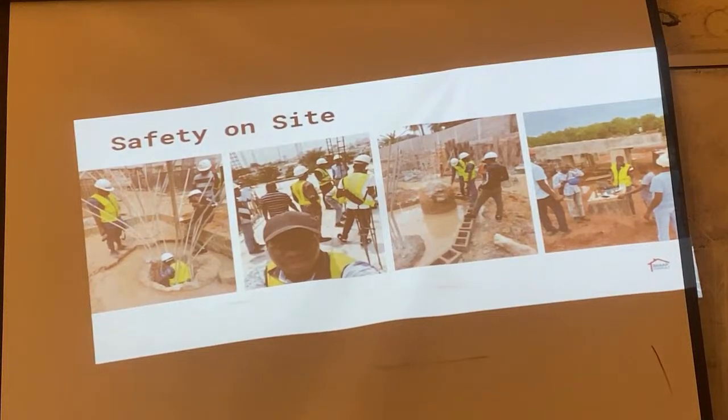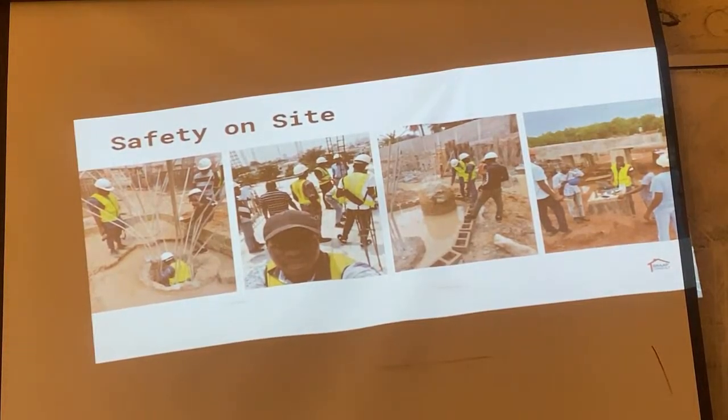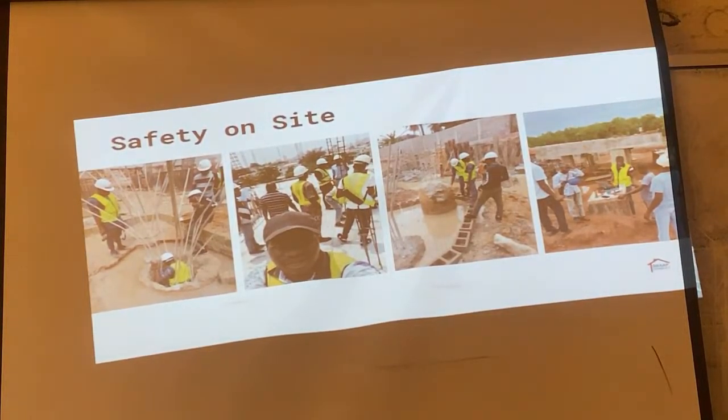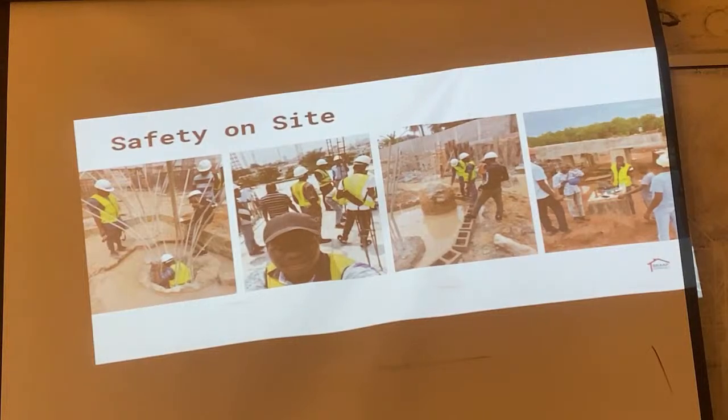We are done with the construction of the building. How do I then know the structural integrity of that building? Do I still need to crush again after I've crushed the first time, knowing that the value I got the first time is maybe just for 25 years? That is why we carry out NDT. That's where NDT comes in. It's not about which one is better. As I was explaining the UPV, the correlation, I still make mention of crushing cubes to create a correlation.